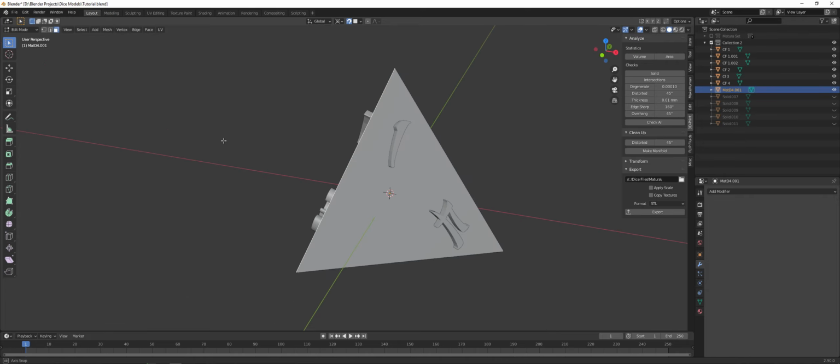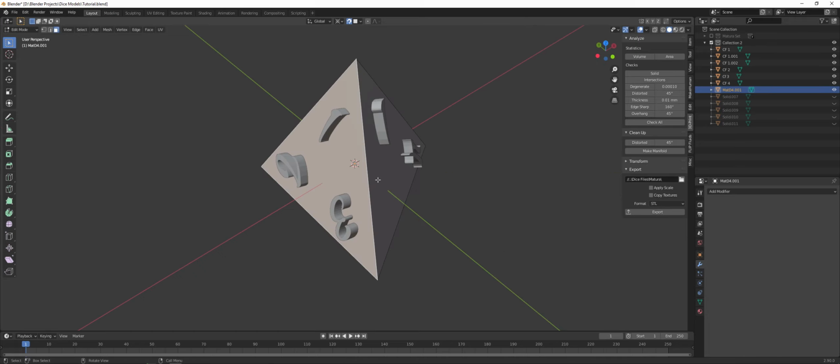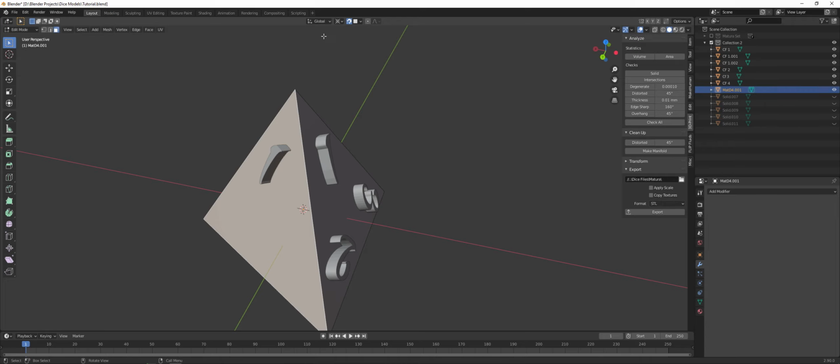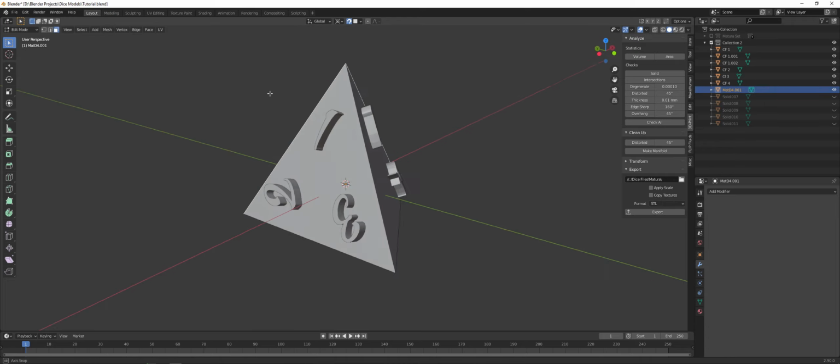For example, this one is gonna be for the 4. So you create a custom orientation with this. It will create one, and you change the name to the appropriate name, the 4, for example. And you're gonna do the same for the one for the 2 with this face, and for the one for the 3 with this one, right? I already have them, so I'm not going to create them.